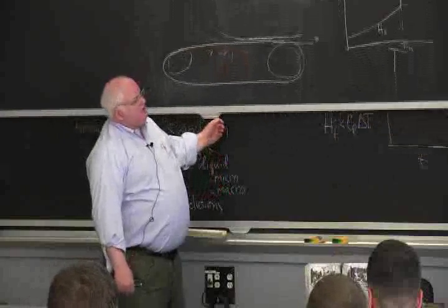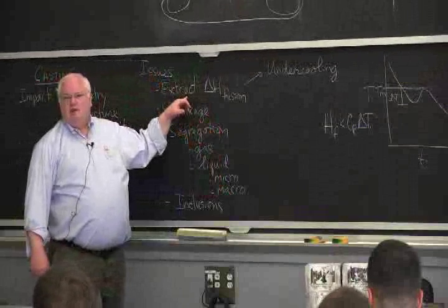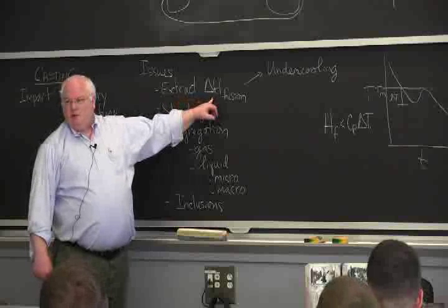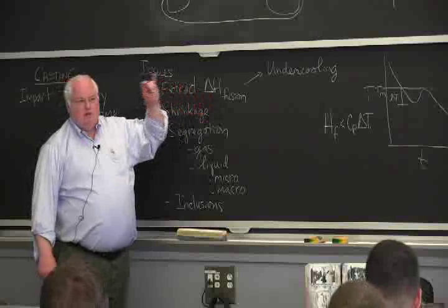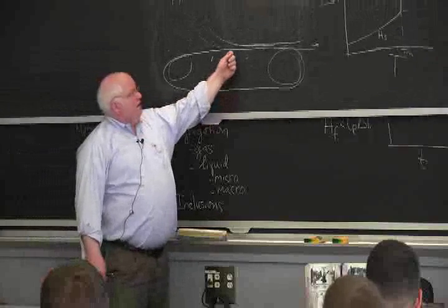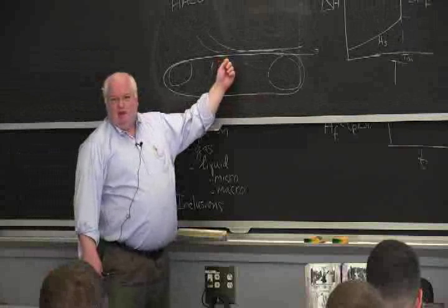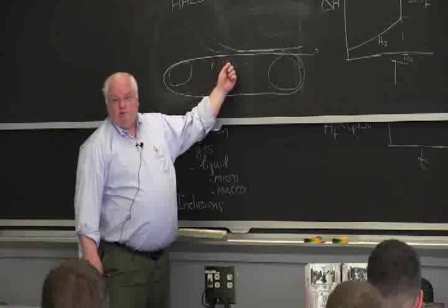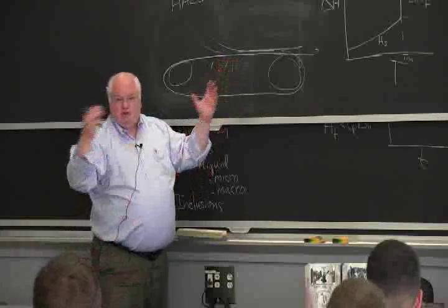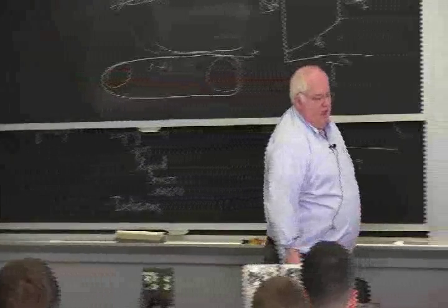Now, why do we do this for copper? Copper has a very high thermal conductivity. It's easier to extract the heat of fusion from something with high thermal conductivity, you can do it in thicker sections. And in this case, they can use 1/8" steel bands. Now, it's a real mess if you break one of these bands and you now have molten copper in contact with water and you generate steam and explosions and other things. So you have to know how to do it.